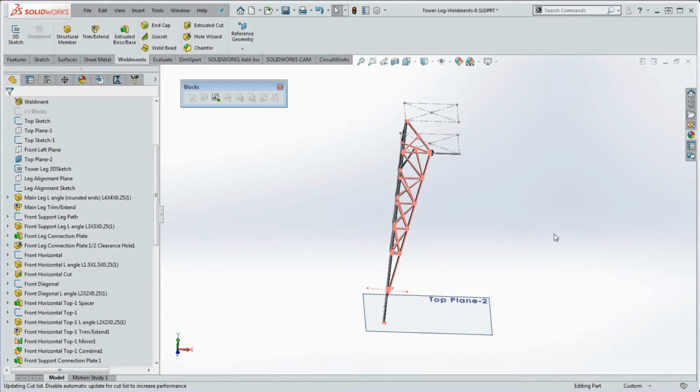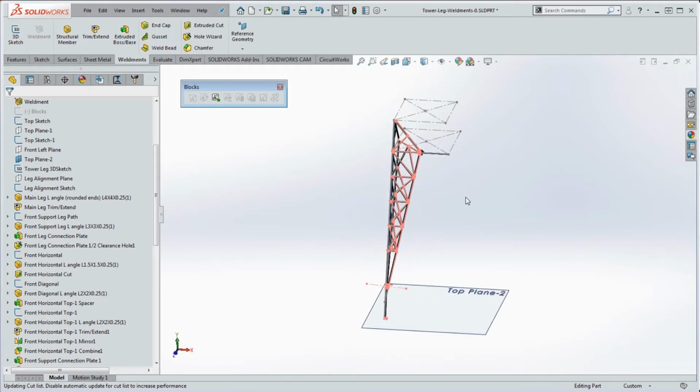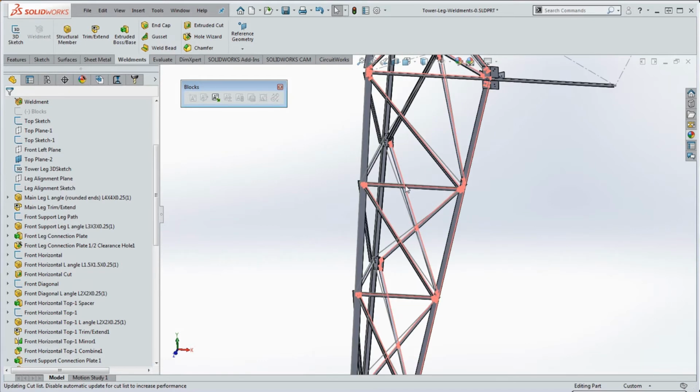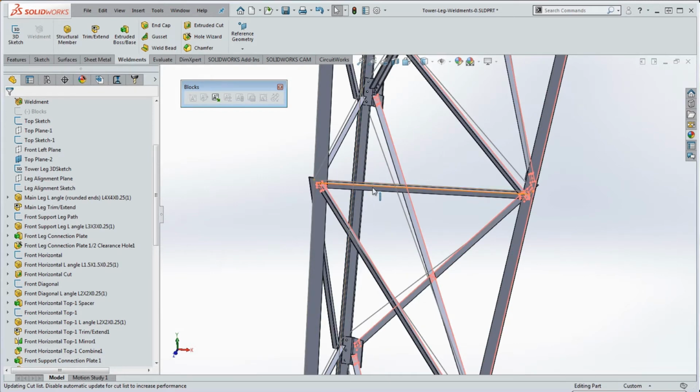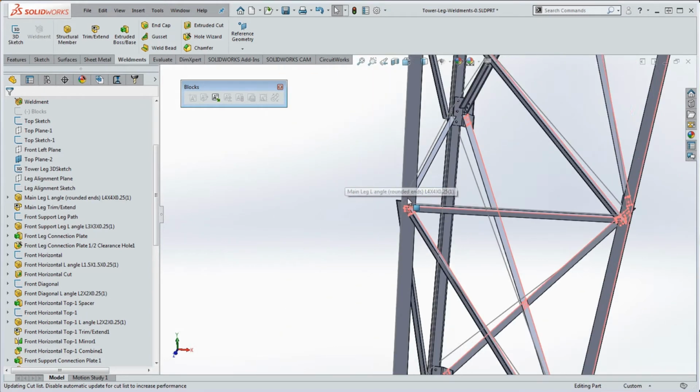Okay, so the question at hand is, we have a 3D sketch in the background, our design sketch or skeleton sketch, and that drives the basic overall size and shape of the model. And we have other sketch elements in here too, which are related. We have our 2D sketch elements in here, which are these pass segment lines in pink, which are helped define by these sketch blocks at the very end of those lines.